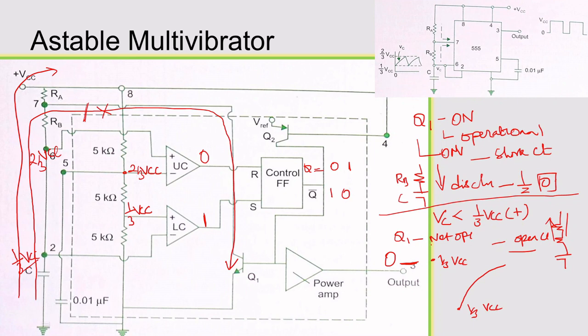Up to that, this is used to charge through this lower comparator logic. So when it gets 2/3 VCC, the next state is going to change. So up to that, what is the output in the third terminal? During the charging period, the output will be high. Understand? During the charging, the output will be high. The logic of 1. Hope you are clear.